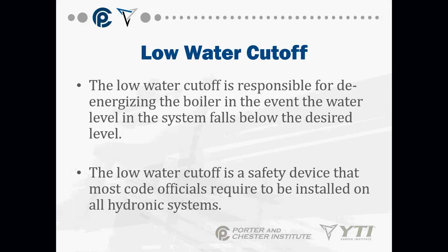Okay? The low water cutoff on a boiler is responsible for de-energizing the boiler in the event the water level in the system falls below a desired level. The low water cutoff is a safety that most code officials are going to require, and believe me, a low water cutoff is pretty much universal. Every boiler has to have one on it, regardless of what state you're in. And those have to be tested every so often to make sure that they are functioning correctly.